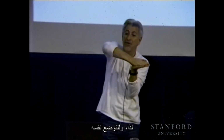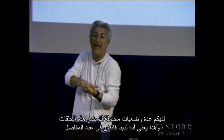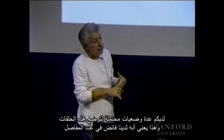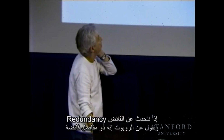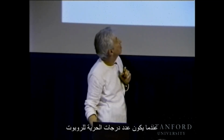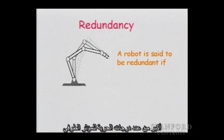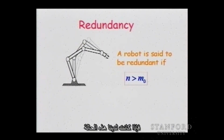So for the same configuration, you have different possible configurations of the structure, of the links. And that means we have redundancy. So we talk about redundancy, and we call the robot redundant if the number of degrees of freedom of the robot, n, is greater than the number of degrees of freedom of the end effector, m0. So if we have this situation, m0 here is equal to 3 and n equal to 4, then the robot is said to be redundant.